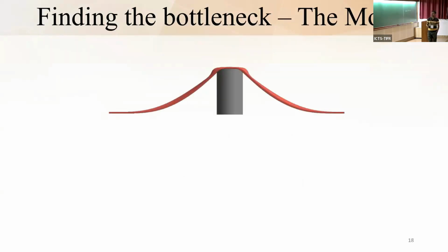And so for that, this is an interesting platform where you have these nanopillars, and you put a single monolayer of some material. Here we put tungsten selenide. Because you are introducing a strain in this pillar region, there is a band gap reduction in the monolayer. And because of the reduction in band gap, if you excite through laser, these excitons will eventually funnel, because this is the lower energy state.